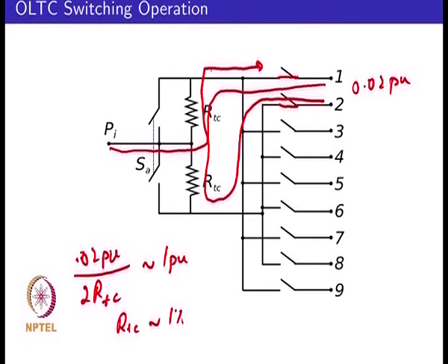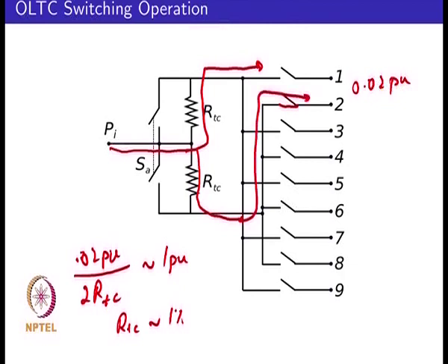So this would be your second condition, where you have closed switch 2. Then under this condition, you could now open the throw 1, in which case the current flow will actually change from the top. It will actually now flow through this particular path, and then you could close switch SA back, and because switch SA is closed, now your current diverts through the switch, which means that the losses in the resistor will be happening only during the transition time.